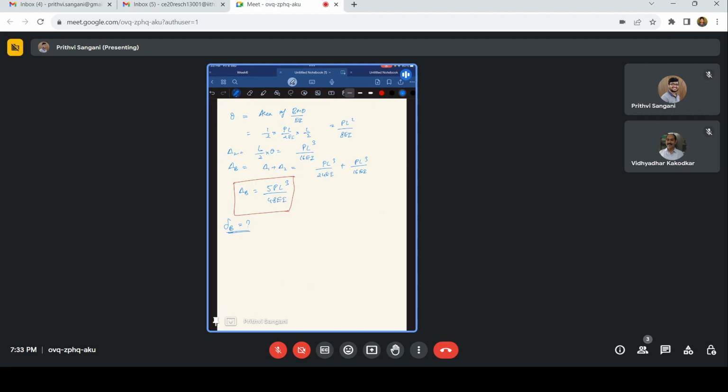Yeah. So this is MB. This also is MB. Again, I want to find the M by EI diagram. So this is my area of the bending moment diagram, or the curvature diagram. So delta B double dash is going to be half. Sorry, there's no half here. It's a rectangle, right? So this is nothing but MB by EI times L times L by 2. So this is quite straightforward: MB L square by 2EI. This is going to be upwards.